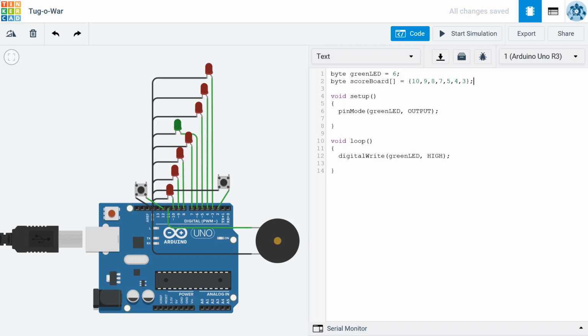Next, just to help you understand how arrays work, we're going to include a line at the very beginning of our setup called Serial.begin. And I'm going to put 9600 here. That's the default baud rate. That's the default rate at which serial communication happens on an Arduino, or most Arduinos. And then I'm going to do a serial print line right here at the bottom of the setup. And we're going to see something that you're probably going to be surprised about.